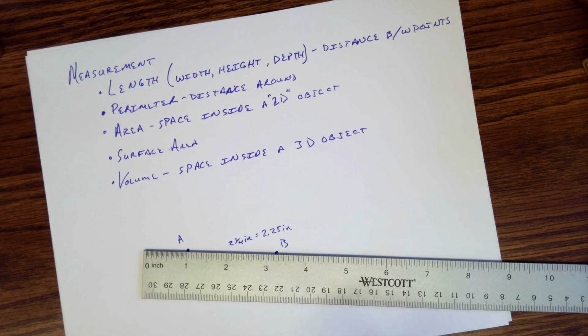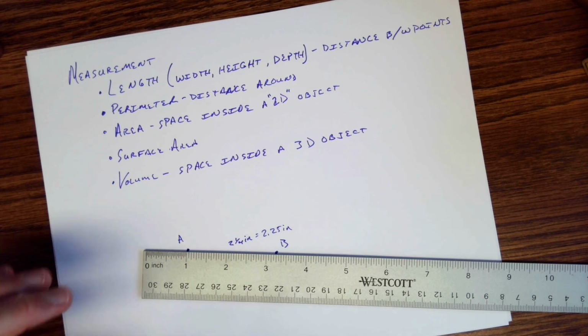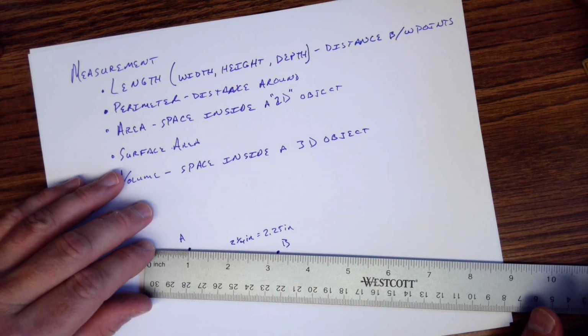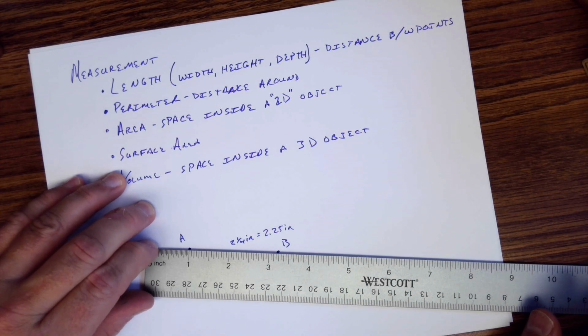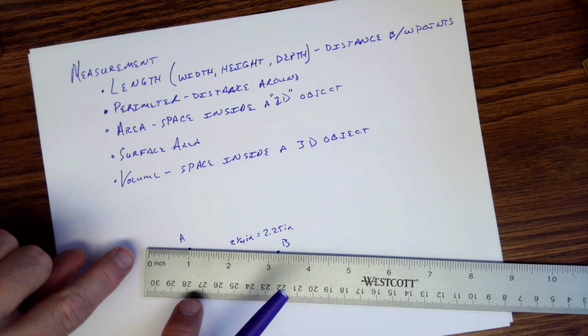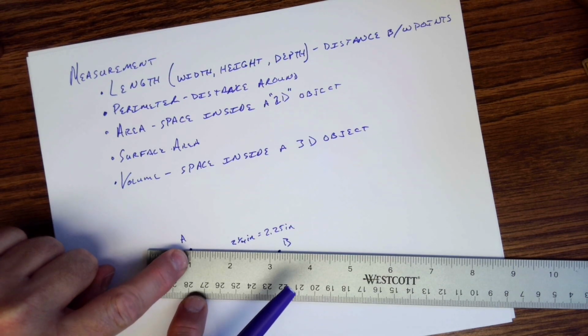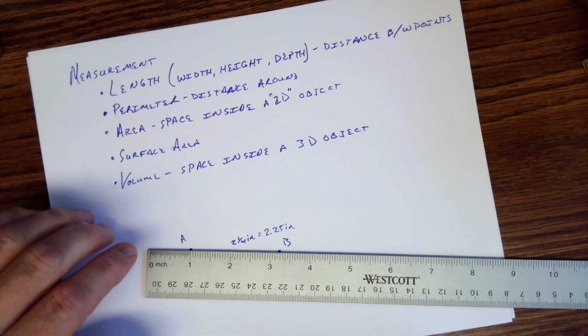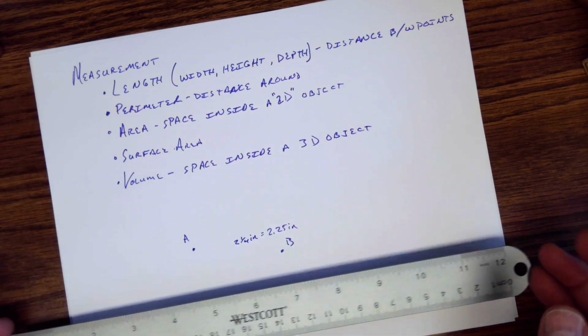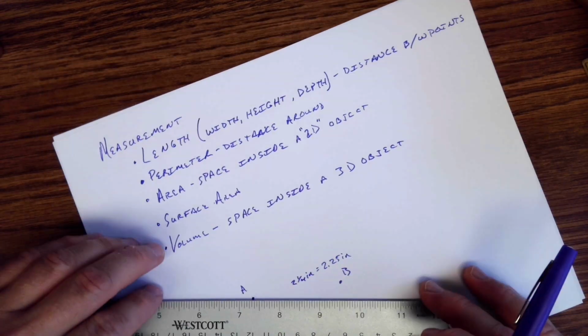And this is something that's actually useful when you talk about working with building materials. If you ever use a tape measure, the tab at the end of the tape measure actually has play in it, and there are actual reasons for that. We won't get into them here, but there are legitimate reasons why there's play in the tape measure as opposed to not being play in there. So anytime I measure something and I want accuracy on my tape measure, I actually don't use the tip of the tape measure. I actually start measuring from 1 for that reason.